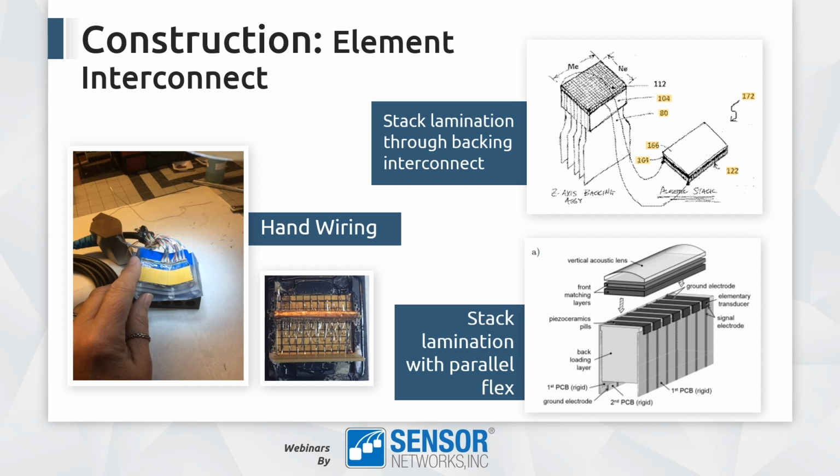which is stack lamination with a parallel flex. Here, the flex circuit is laminated between the piezoelectric and the backing. This is a simpler approach than through backing interconnect, and it works very well for linear arrays, and works well for many matrix arrays. There are some limitations on the density that you can achieve, because there's only one layer of flex circuit to bring all the connections out, and as you start having many hundreds or thousands of connections in a small area, that can be problematic.